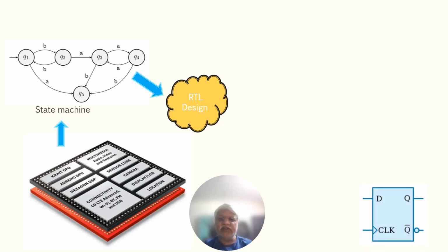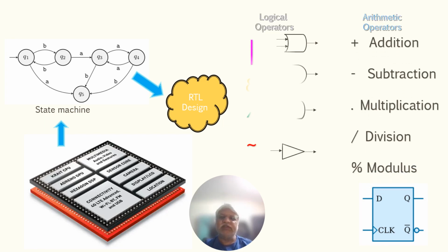An example is shown here. Sometimes these D flip-flops can have more ports like set or clear. So the phrase register transfer embedded in the RTL acronym refers to how data transfers between registers, which enables logical operations and mathematical operations on the data. The data stored in the register can be used as input to a logical operation, and the result of the operation can be stored back in another register.